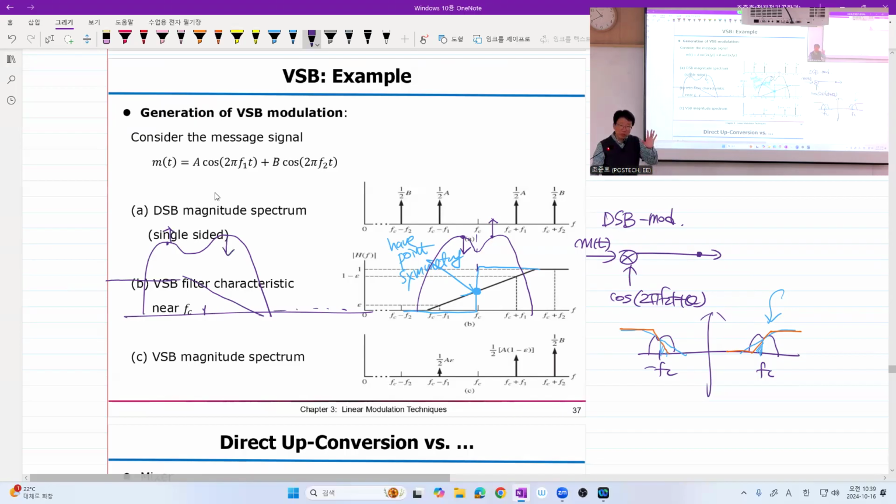In your coherent demodulator, what happens? These two spectra are right-shifted and left-shifted and added. Now what will happen? This one with the left side de-emphasized is added with this one with the left side emphasized. So they have perfect compensation of the amplitude.